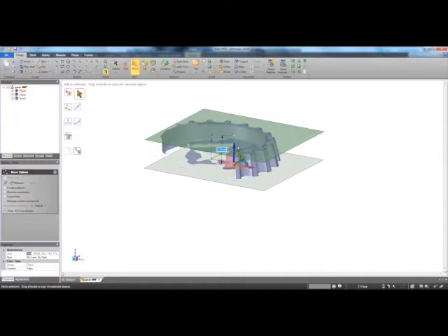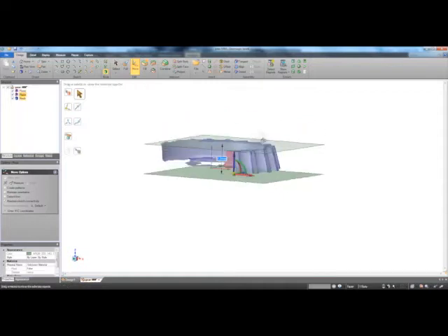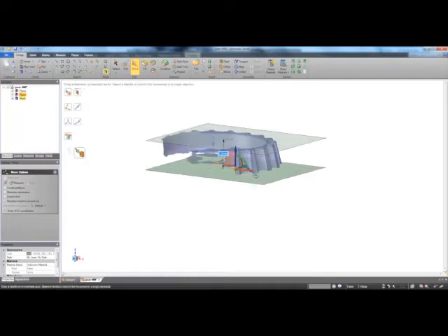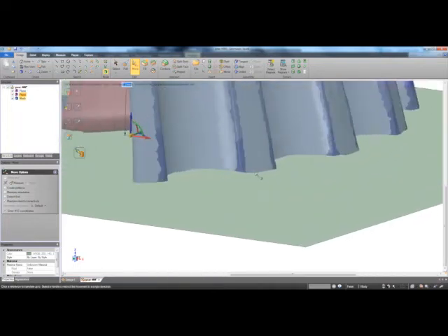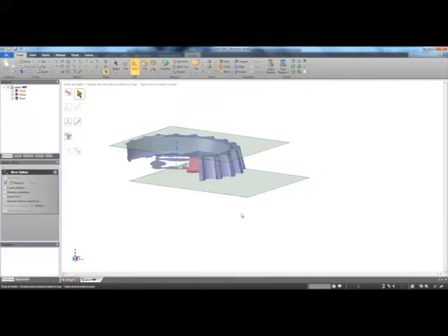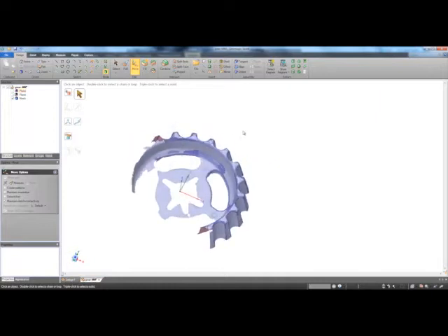So it's identical to that top plane, but I keep the top plane, I just make a copy. I can go ahead and click on Up To, which just says where do you want to move that plane to. I left-click on the mesh, you'll see a little triangle right here, and it just snaps that plane in the Z direction to that location. So on the left hand side you'll see we've made two planes. I'll just go ahead and hide those.